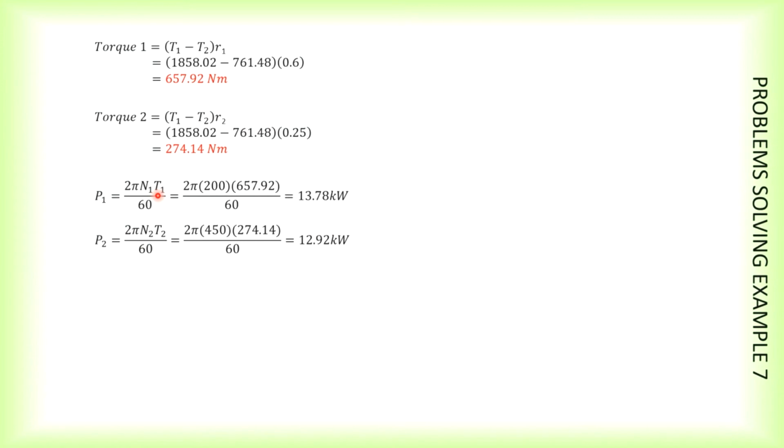This is the input shaft, the larger pulley. This is the output shaft, the smaller pulley from the previous diagram. If you take the difference, you will be able to measure how much power is lost when transmitting from the larger pulley to the smaller pulley. This is quite an amount, as compared to the 0.01 just now.